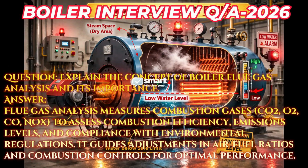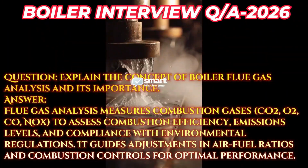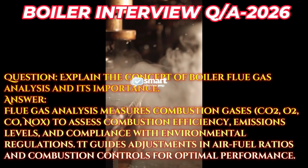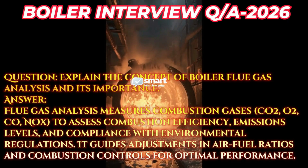Question: explain the concept of boiler flue gas analysis and its importance. Answer: Flue gas analysis measures combustion gases, CO2, O2, CO, NOx, to assess combustion efficiency, emissions levels, and compliance with environmental regulations. It guides adjustments in air-fuel ratios and combustion controls for optimal performance.